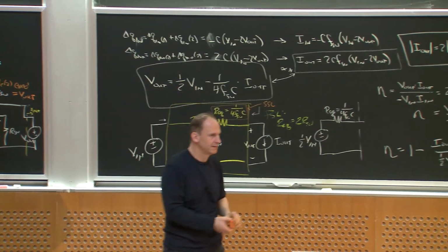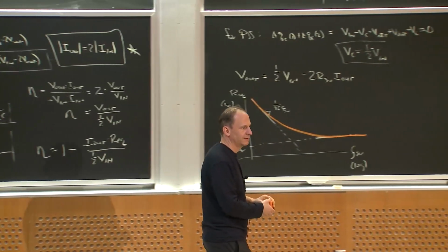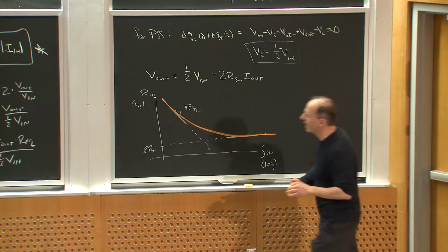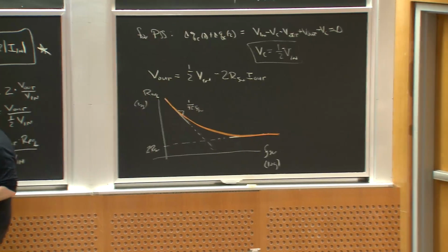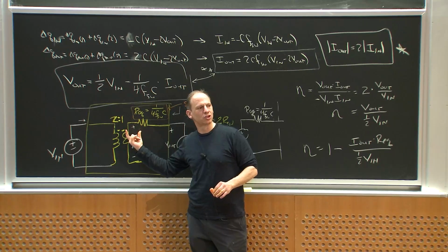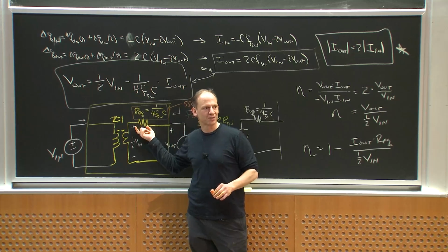Yeah. Now that you're switching quickly, can the duty ratio change the conversion ratio? Well, yes, but only through the action of essentially what this resistance is. For any given converter, there's a duty ratio that'll give you the lowest output resistance.